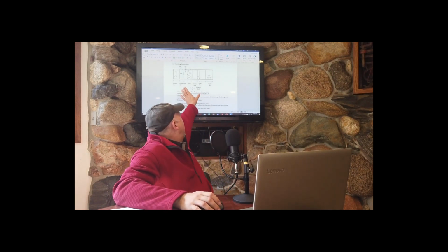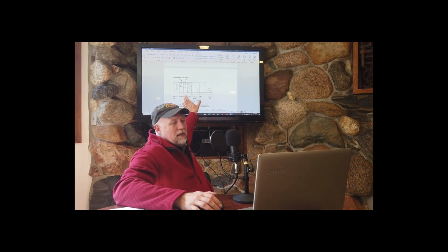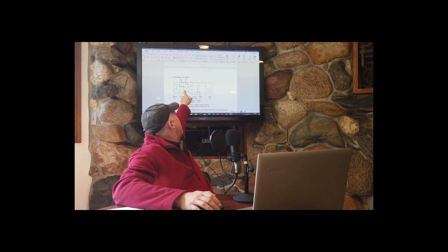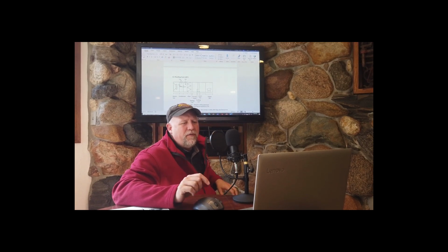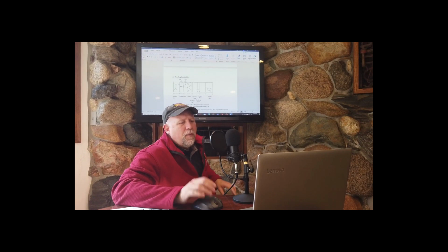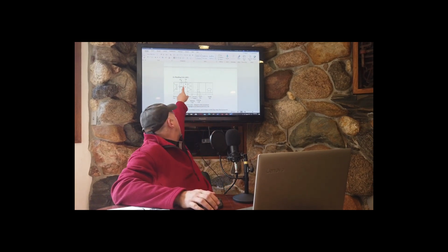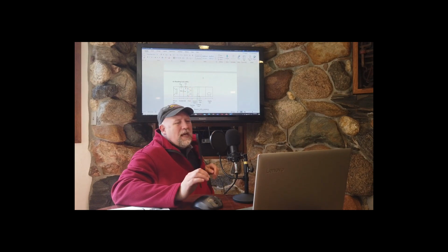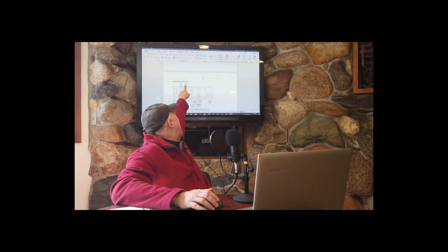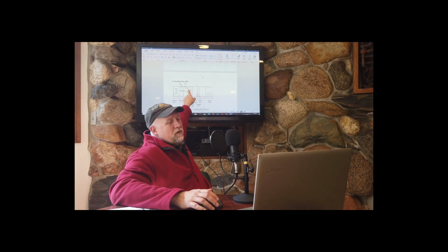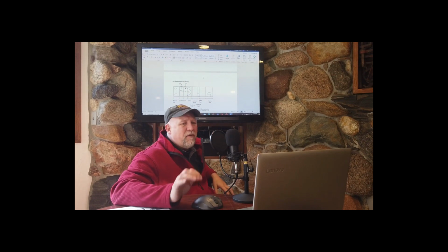So from a side view, as we're looking at this diagram, return air comes in here to the return air fan. It goes through the economizer. The purpose of the economizer, which I believe we've touched on before, but I want to review it again, is this is where we are going to mix this air, but also when it's cool outside, I can bring in outside air that's cooler than the space and use that for air conditioning.